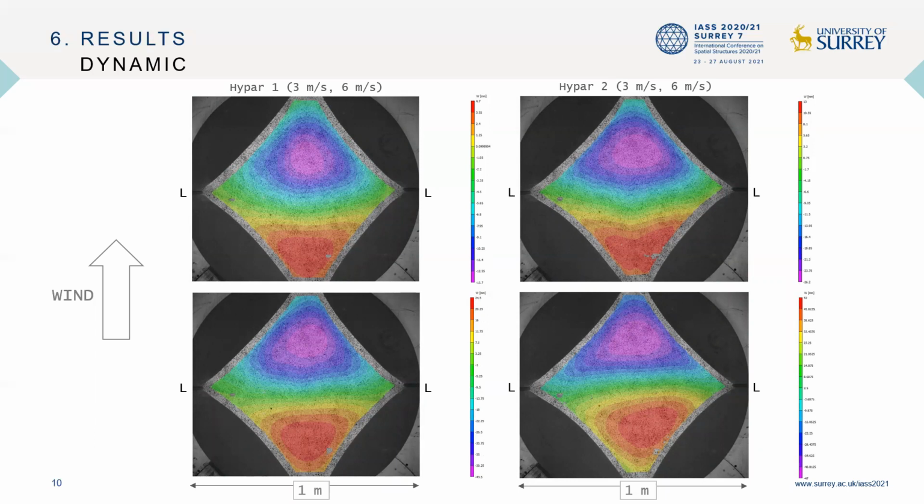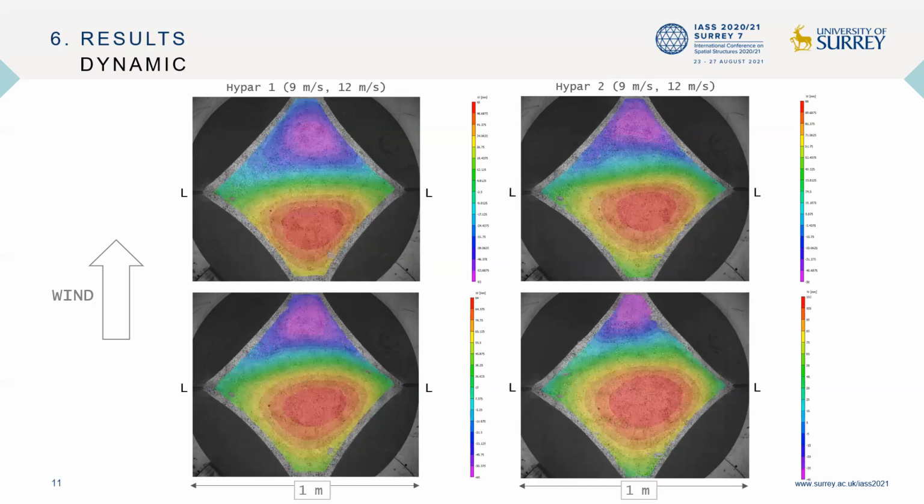Two possible phenomena were possible in the case suction appeared. First, a positive lift force due to the faster flowing winds above the surface in comparison to the area underneath. Second, the appearance of a separation point of the flow causing a lower pressure area, which also influences the pressure drag.